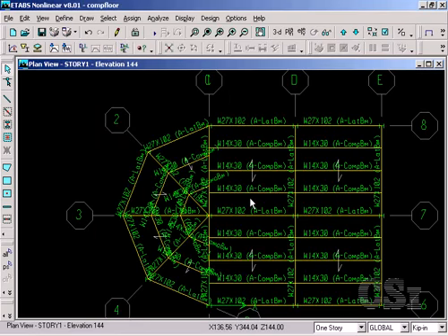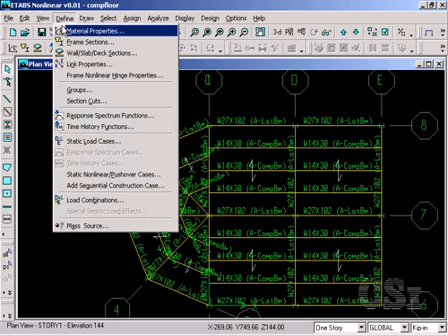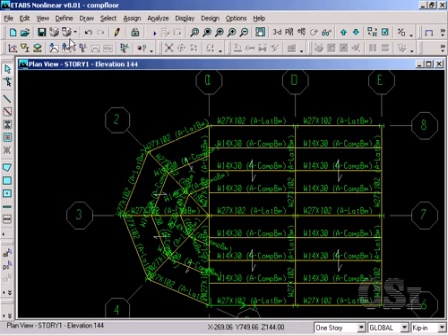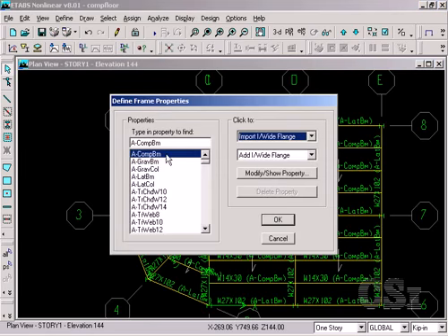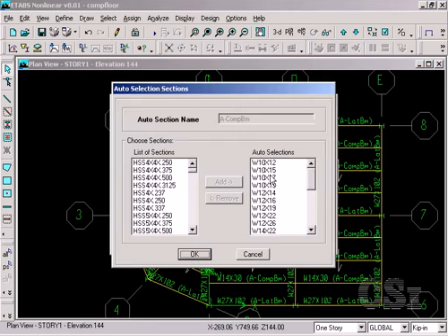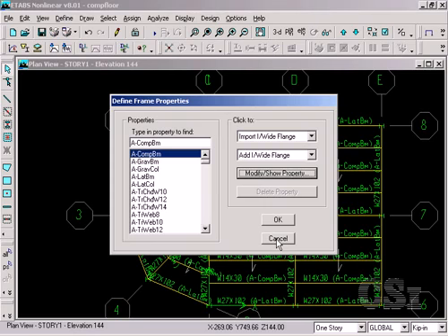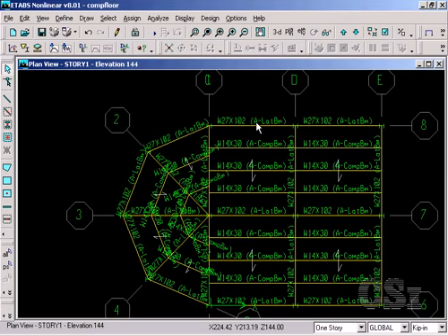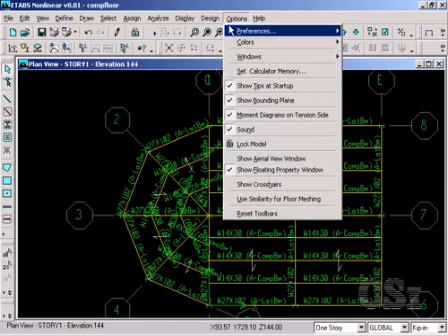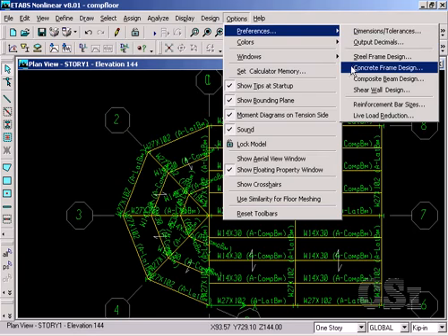The Auto-Select Composite Beam list is a predefined list of sections, which range in size from W10x12 to W27x84. The W14x30 initially selected is simply the median size member in this list. All the design controls are available through the Options, Preferences, Composite Beam Design command,